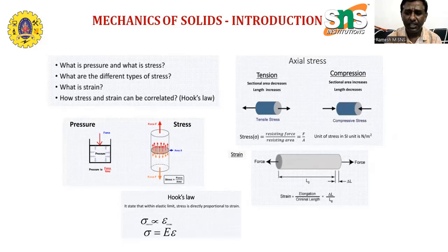Why is it a negative sign? Let's take our material and pull it in tension. The direction perpendicular to the pulling direction is called the lateral direction. One dimension is increasing while at the same time the lateral dimension gets reduced. If it is compressed, the lateral dimension elongates. So one side increases and the other decreases, and vice versa. So Poisson ratio is equal to minus lateral strain to the longitudinal strain.